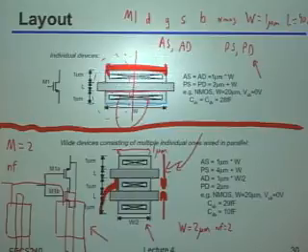So when you do M equals 2, does it also capture the spacing between the 2 transistors? Not necessarily. You have to be a little bit careful between what you put into Cadence and what actually pops out in the model, which is why I'm never a big fan of GUIs. I actually like to look at in text what's really happening. But basically, in SPICE, if you were to take this instantiation and just say M equals 2, it doesn't know anything about the space. It literally just takes the exact same model and puts another copy of it directly in parallel. So it won't model anything about extra wiring or anything like that. It's a good question.